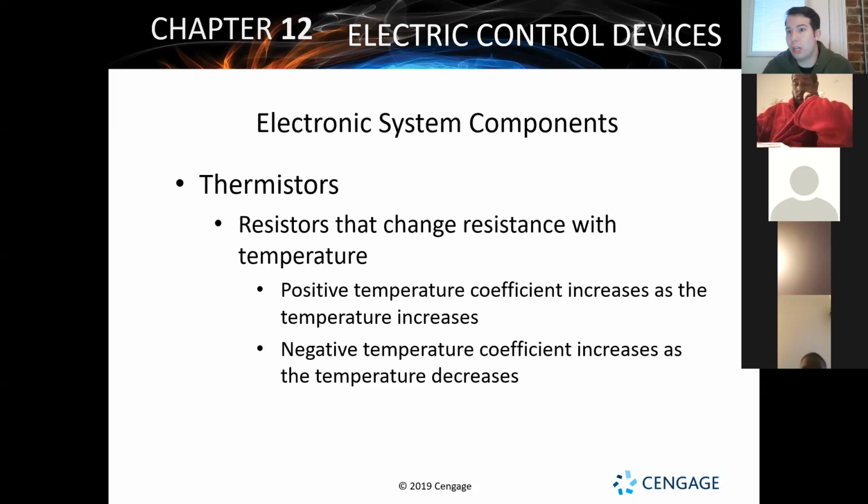About every degree you increase temperature on a thermostat, you're adding about 3% to the energy bill of a household. So it's really, really expensive to operate a system that way. So instead, having these thermistor controls is pretty much what's allowing modern systems to be really, really energy efficient and make sure that they send temperature only where it needs to go.